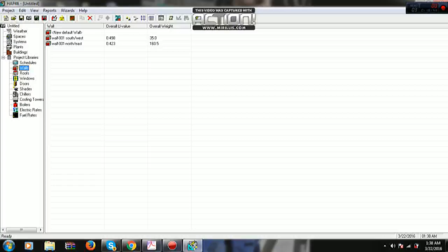And it is a very important procedure. First of all, initial settings, and this is the second part. Before starting any new project in HAP, you have to do all these settings, creating the U values, setting the U values, and setting the load profile, which I'm going to explain in the next part of